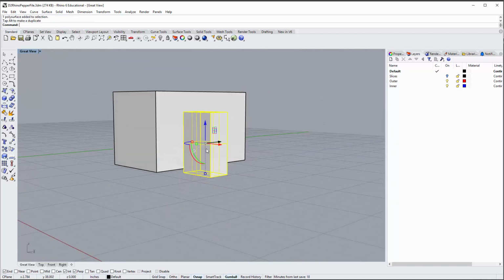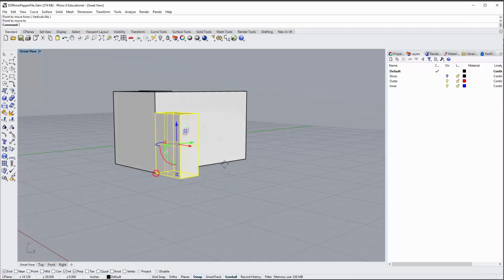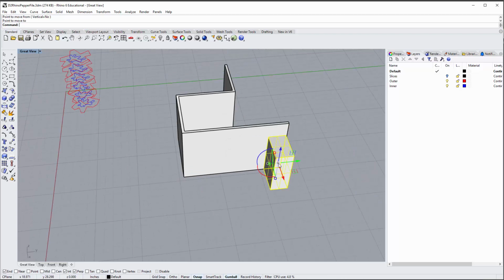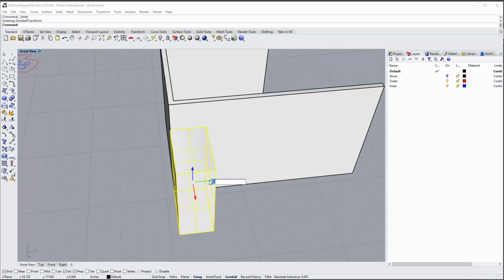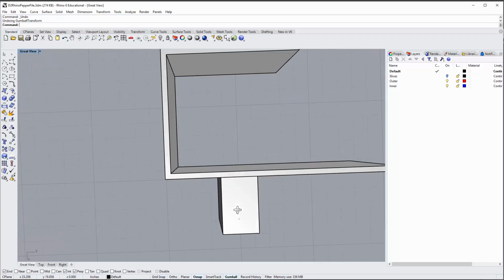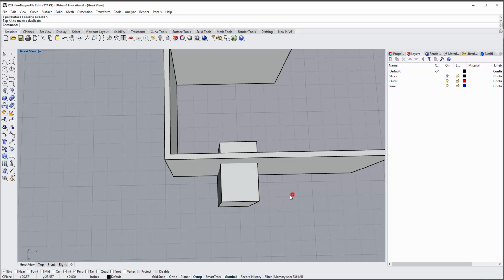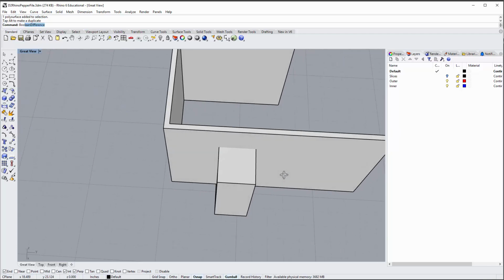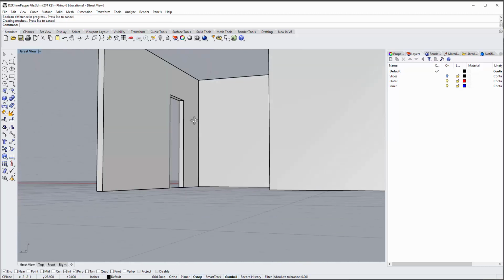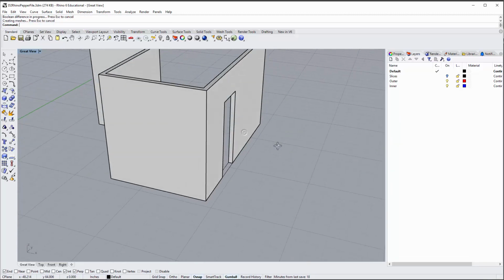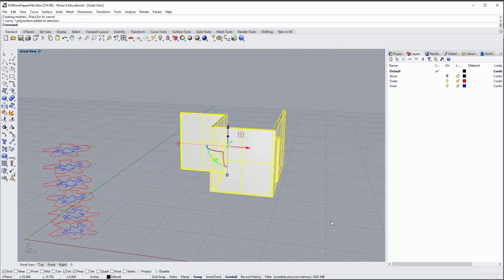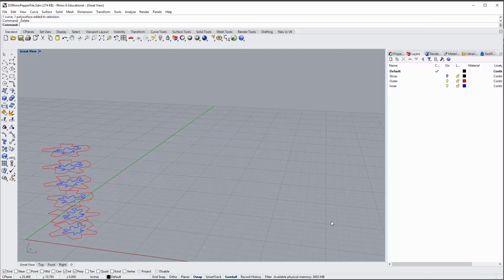I'm going to undo my ortho. And we can then, for example, move, right? I can snap this to a specific location. I can move it a specific amount by using the arrows. So let's say, let's move it just like 3. Okay, so you know this is exactly its position in the plan, for example. That's the position of the doorway in the plan. So then you would just do a Boolean difference, take this, subtract it, you have your door. Your doorway, at least. Okay? So I think that's specifically with the Boolean difference or subtraction, that's where it comes in really handy.